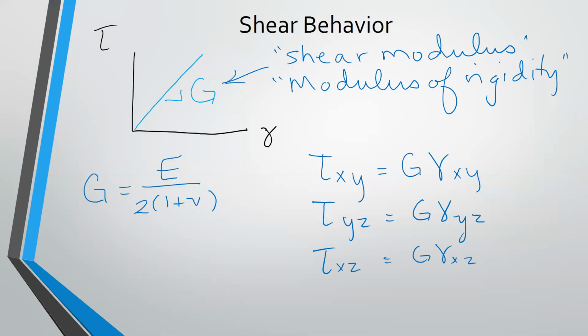And you can think about that in terms of how something deforms. If you were to take a cube and you slide one plane past the other, the other directions don't slide. So this could really use a visual aid. But if I have a cube and I slide the top and keep the bottom steady, that thing will have rotated, but in this plane, it's still perpendicular.